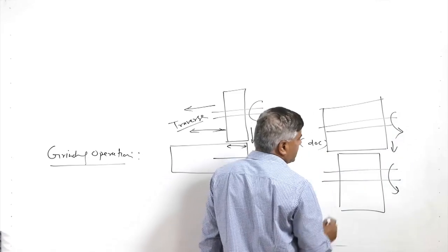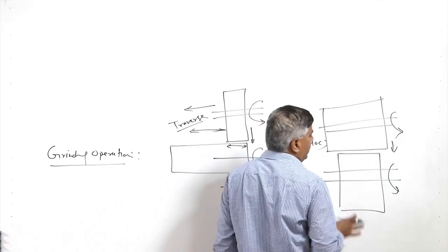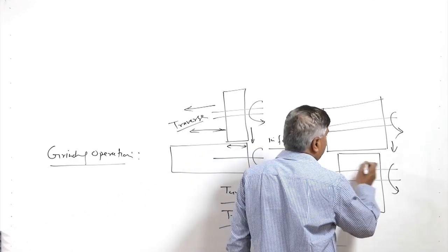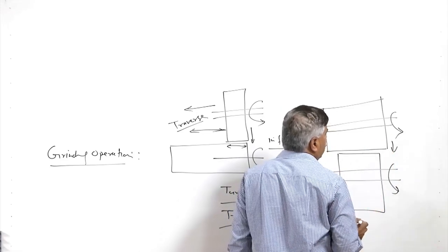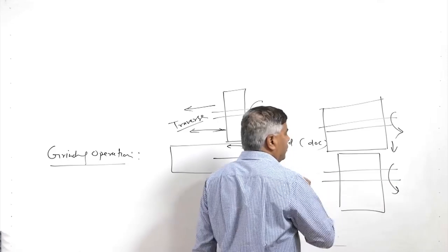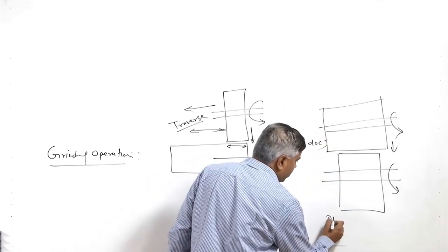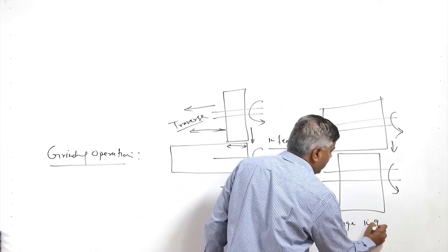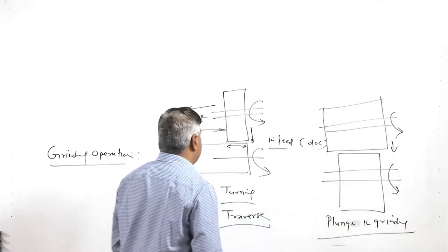Since in this case the width of the wheel is bigger than the length of the workpiece, just a radial in feed is needed for giving the depth of cut, and no traverse movement is required for this purpose, and this kind of grinding is called plunge grinding, or plunge cut grinding as it is also termed.